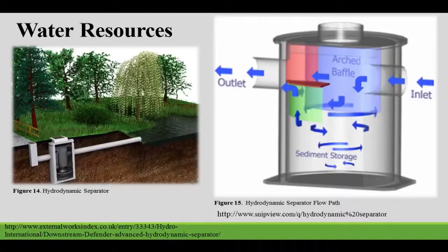And the hydrodynamic separators we'll be using, I'll just quickly explain how these work. Water enters in the inlet, and it swirls around. The sediment drops out, and then the clean water flows out. It's kind of like a swimming pool. You make a whirlpool, and all the dirt goes to the middle.